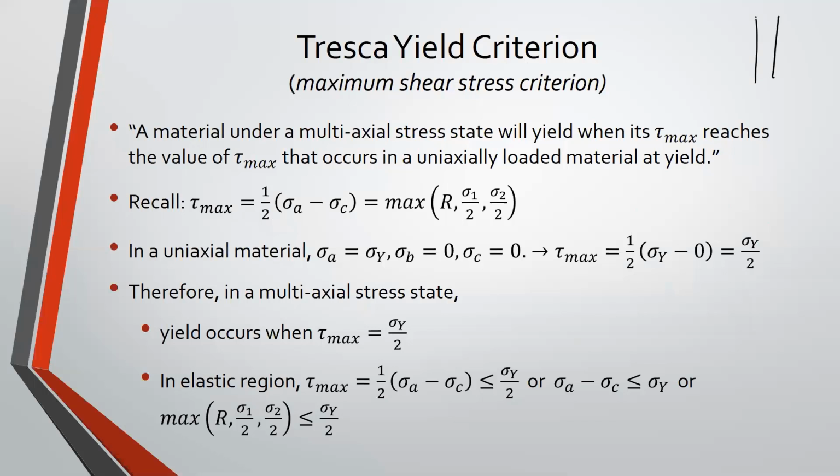So I have this material and I apply a yield stress. That yield capacity, that normal stress, is not necessarily what's causing it to fail. It's not failing because the normal stress is larger than the yield stress. We say that, but that's not actually what's happening. What's happening is that there's some maximum shear stress along this 45-degree plane, and that maximum shear stress being exceeded is what's causing it to yield.